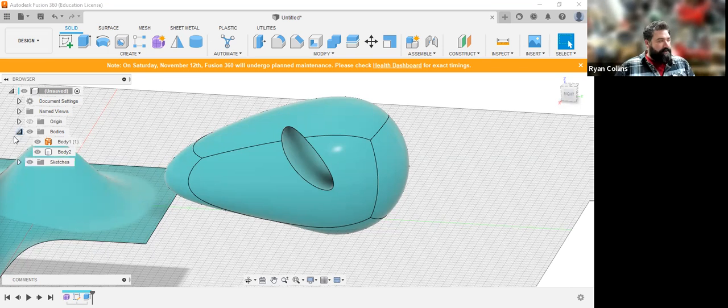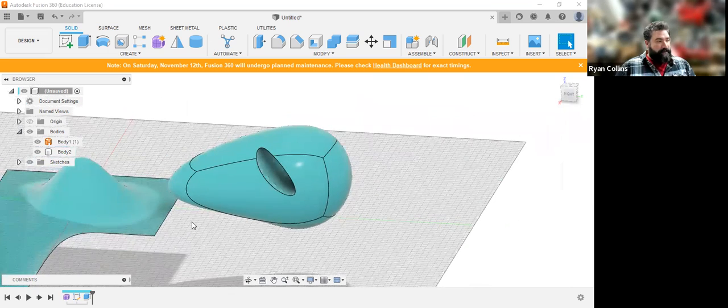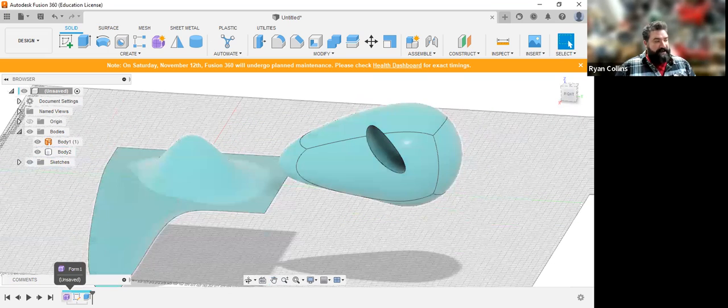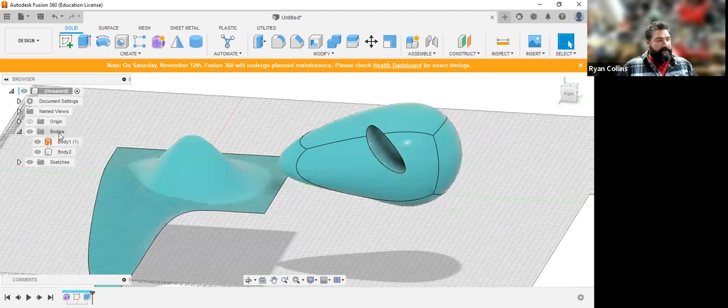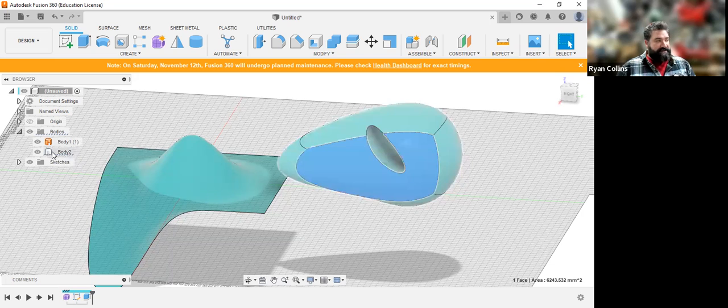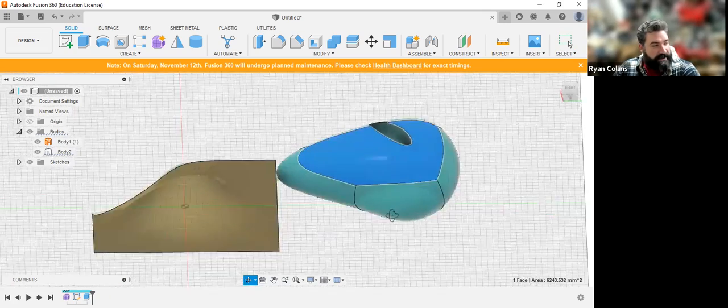Let's go ahead and mess with this. Oh, by the way, despite that being one single form creation, look at my bodies. It's created two different bodies. If I join them, they'll be one, just like normal. But it also shows two different things. One is a body, the weird quad ball. It has the solid icon. It's a solid cylinder, because it is a solid three-dimensional body.